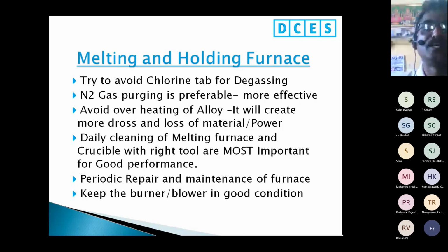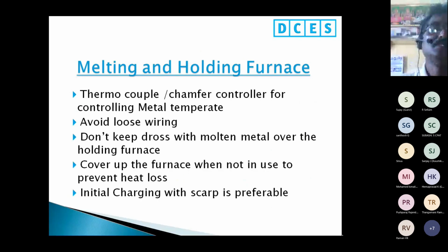Periodic repair and maintenance of the furnace should happen properly. Keep the burner and blower in good condition. See, melting and holding furnace. A thermocouple or a chamber controller for controlling metal temperature should be used. Avoid loose wiring. This also we sometimes see on the shop floor, a lot of loose wiring.